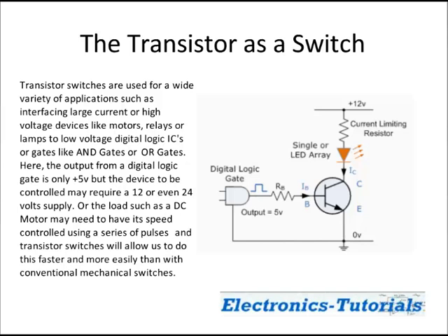And the concept here is that if the transistor has a positive value on its base, which is the lead denoted as B on the transistor at the right-hand side, then the transistor will turn on. And when the transistor turns on, it acts like a switch, and then current can flow from the 12 volts through the current limiting resistor, through the LED, through this transistor or switch, and then it completes its path to ground. And that's basically how we use a transistor as a switch.